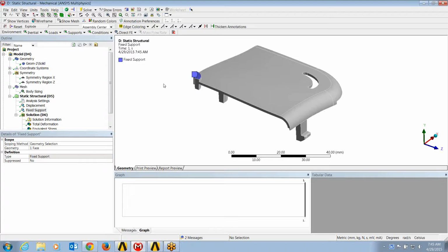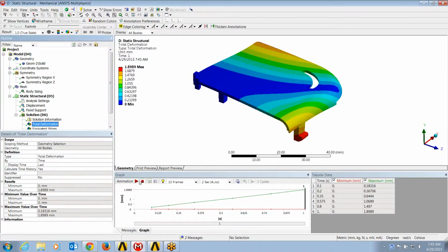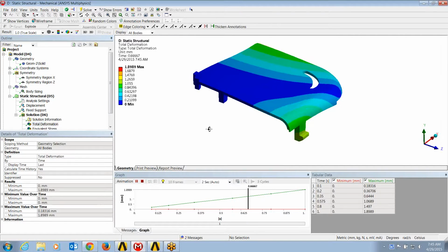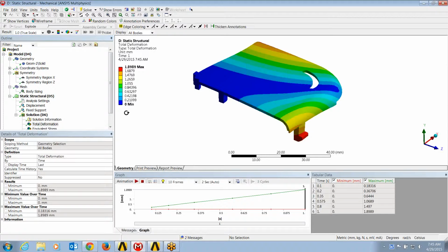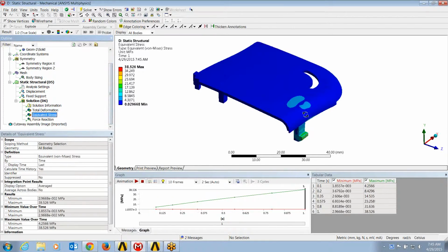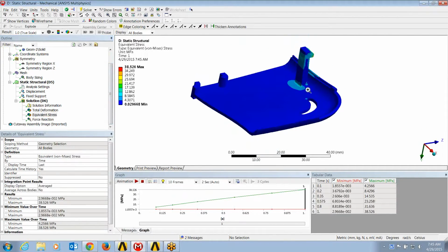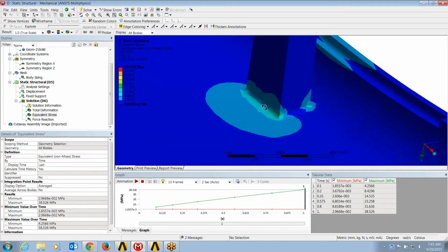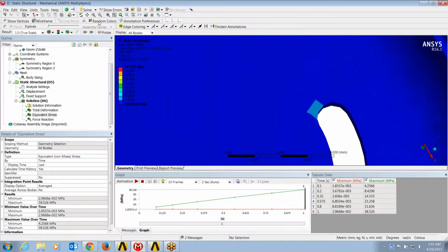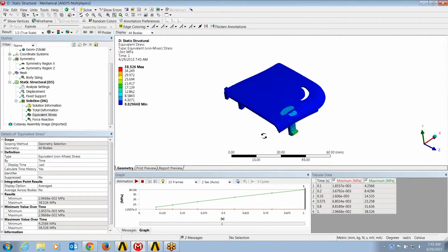And many of you may be running these types of simulations, and you can get the deformed shape and the deflection out of this, can verify that that part is behaving as you think it will in the assembly, and even predict the stress in that post here, and see some elevated stress state there, but really nothing that is of concern from a design standpoint.